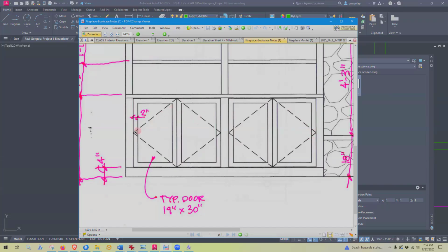So what you are doing when you are showing these dashed lines is telling whoever is reading your drawing where the hinges are on this door. And this applies for all doors, like a door into a room. When we're drawing elevations for a door that goes into the room, you will have this same thing. Or often on windows, if you have windows that open out or into the room, you'll show that dotted or dashed line to indicate where the hinges are on your drawing.